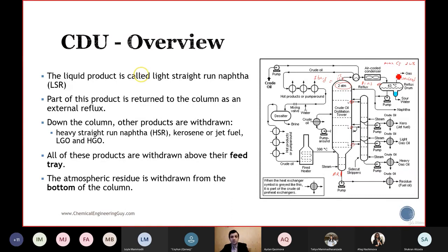What we should do is decrease the temperature to liquefy the naphtha, or increase pressure. That's why it is always desired to have the highest pressure at the top as much as possible and lower temperature. Also, we have to consider the C4 spec in naphtha. If it is also more than enough, then you need to decrease the temperature to evaporate the LPG to remove it as gas.